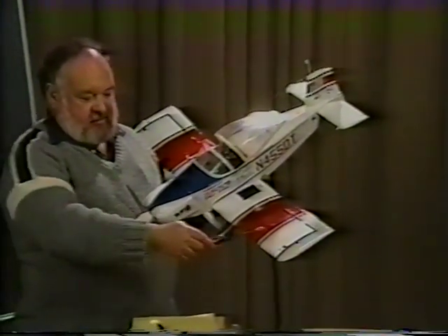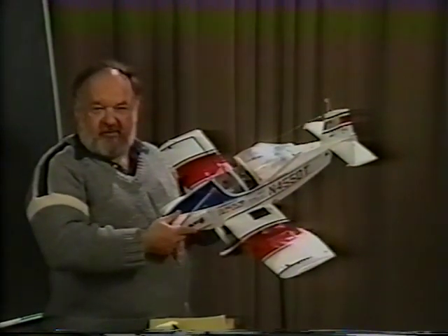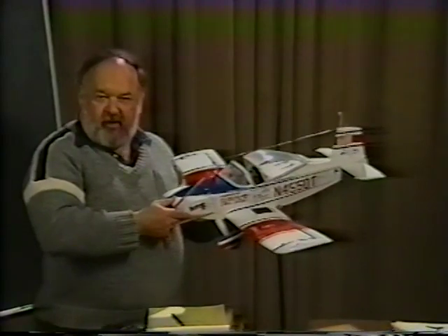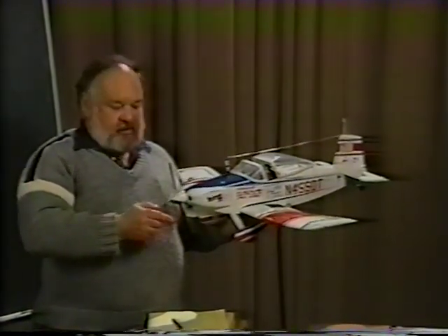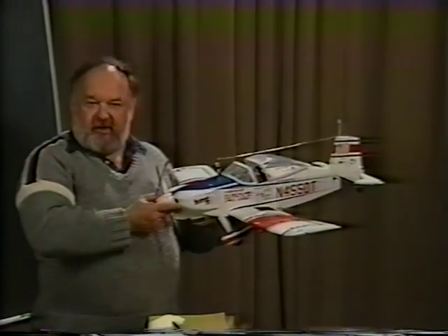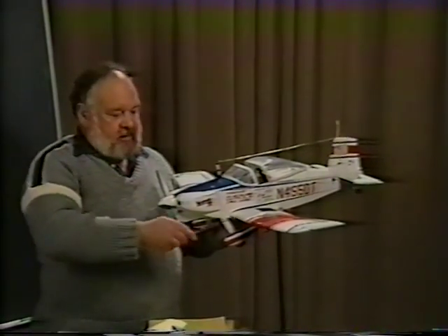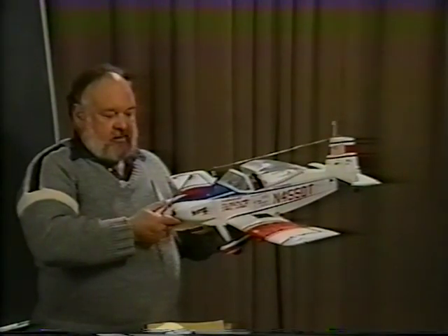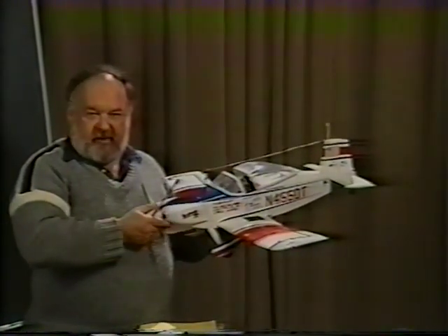John Thorpe has a constant chord wing. The Reynolds number at the tip is the same as at the inboard section, so that's quite good. But he does have this break in here, which from a stall pattern standpoint isn't ideal, but from a structure standpoint was quite good. He has an inboard section of the wing that he could make as a one-piece spar going all the way through, and the first set of joints on the spar isn't until you get to the break in the wing itself, where the spar can go down to be thinner and lighter.